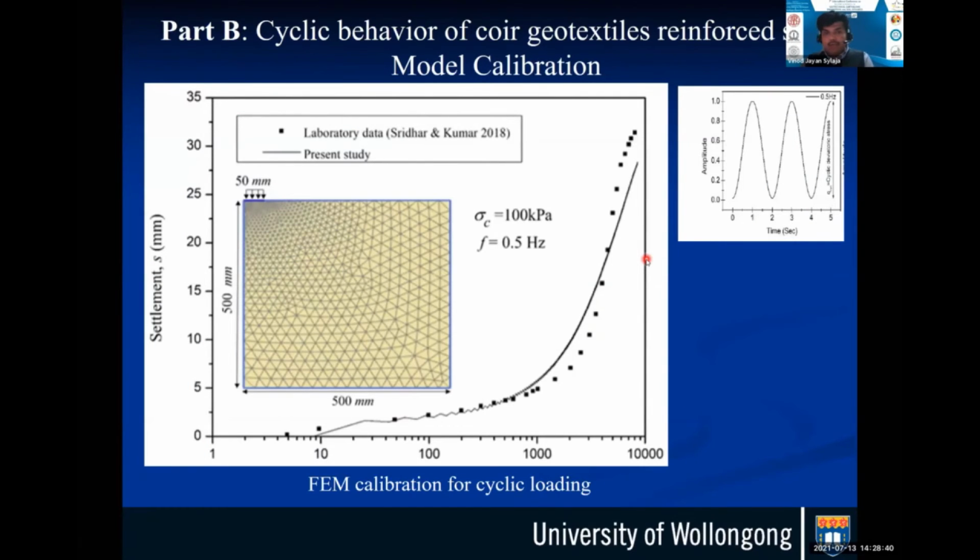All right, with that, I have only 5 minutes here. So let's quickly move on to the cyclic loading of Coir Geotextile reinforced soil. We went through a bit of a challenge here without experimental data: how are we going to model the Coir Geotextile reinforced materials in a finite element model, in Plaxis software. Luckily, we were able to find one piece of literature by Sridhar and Kumar looking at the cyclic loading of a Coir Geotextile reinforced soil in a fully immersed sand condition. So we picked that to calibrate our numerical model.